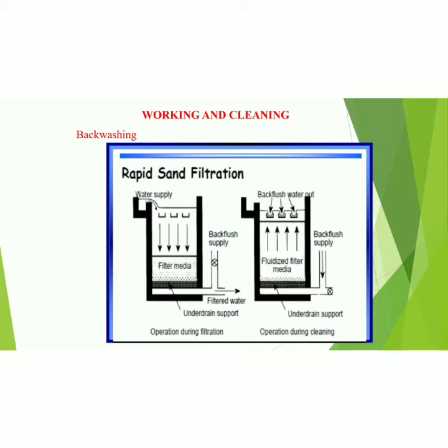Backwashing is nothing but supplying water from the bottom, so that after filtration you can clean the filter media.